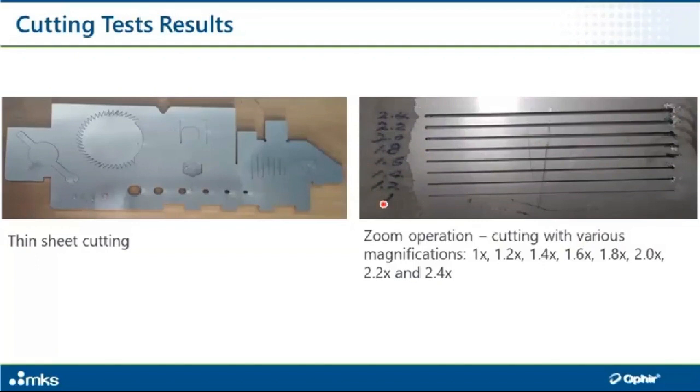And 1x magnification, you get the most narrow width of the cut. So according to your application, you can choose which width you would like to have, and accordingly you adjust the lens so you get your optimal cutting conditions. This is the principle of a zoom lens. As you can see, it's very convenient and it's very useful.